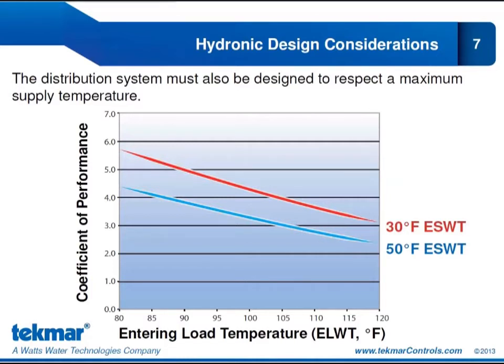The rule of thumb for heat pump systems is that we want to steer away from any design temperatures that exceed 120. Now, that's for R410A refrigerant. If your heat pump uses a different type of refrigerant, then you may have a different maximum design temperature that you can use. But the general rule of thumb that applies to most heat pumps is 120 degrees Fahrenheit.